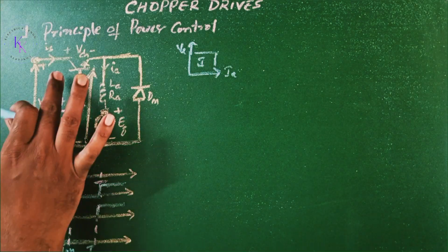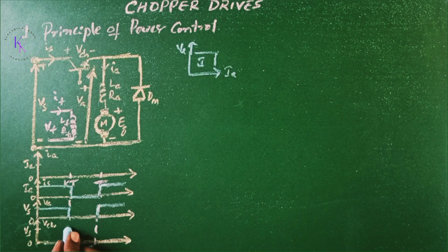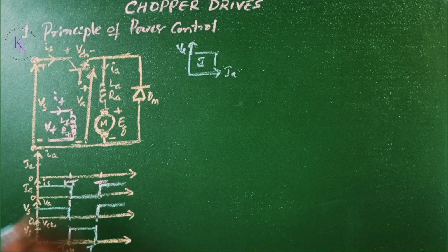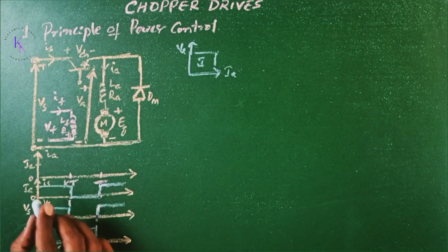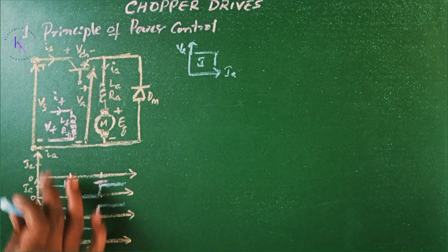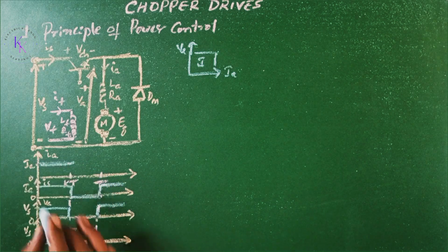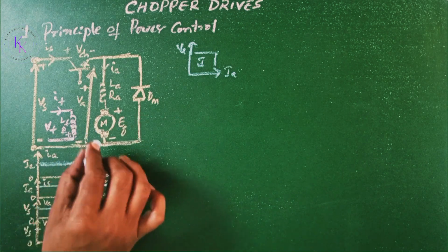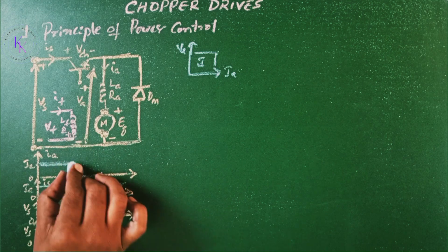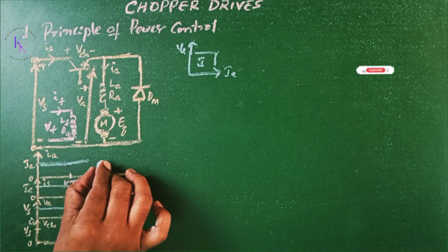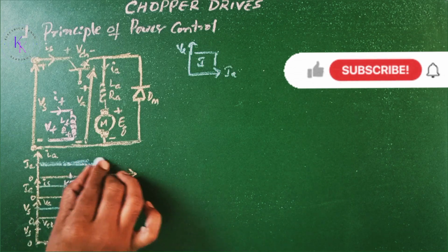When the chopper or transistor is off, the voltage appears across the chopper. The current through the armature Ia will be constant. When the chopper is on, the current flows, but when the chopper is turned off, due to the freewheeling diode and the highly inductive load, the current will flow through the motor, so the current is available even in the turn-off period of the chopper.